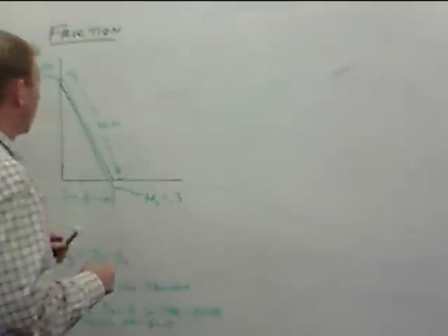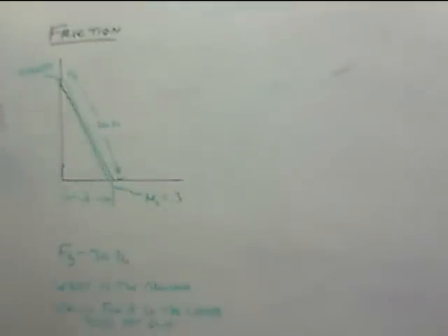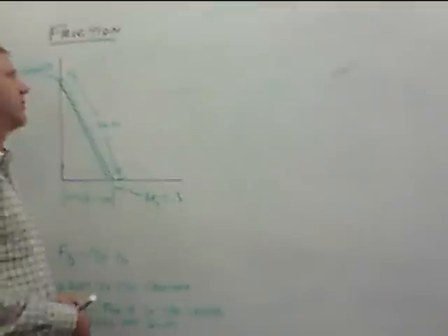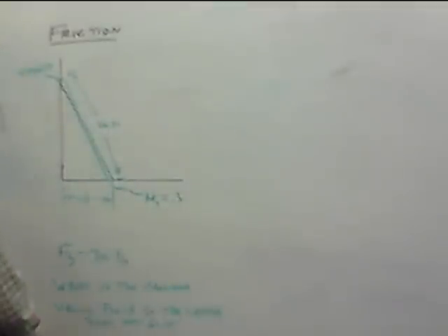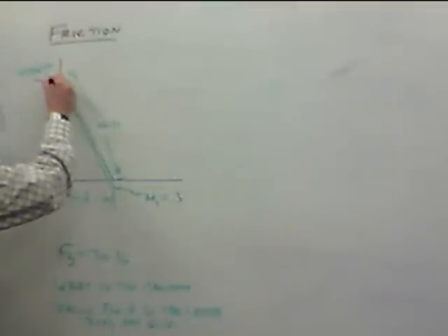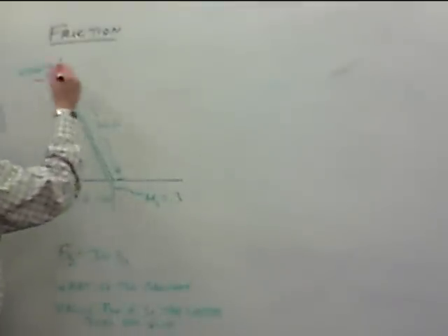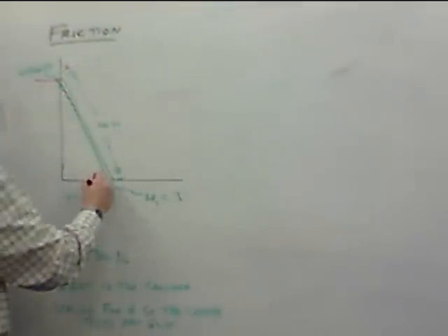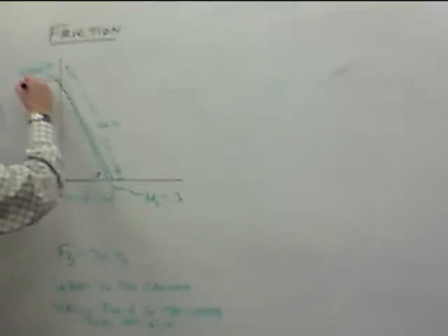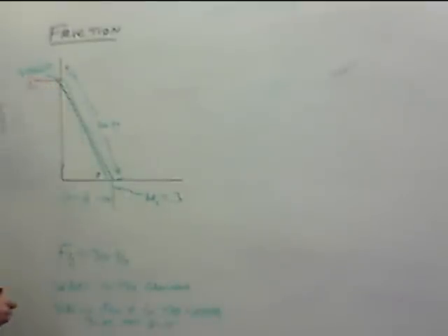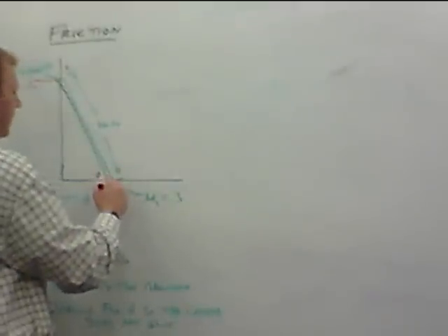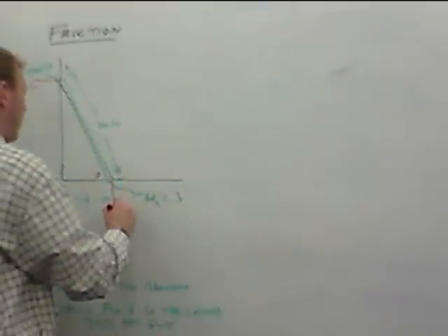All right, so the trick here is, again, the free body diagram. We have a smooth contact here, okay? Just like we talked about any other support forces, that's going to give us a force acting here. We call this point A at the top, point B at the bottom. So this will be A in the X. Point B, we also have a contact surface here, so we're going to have B in the Y.